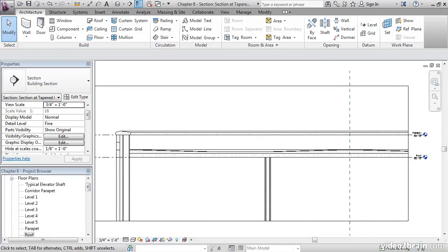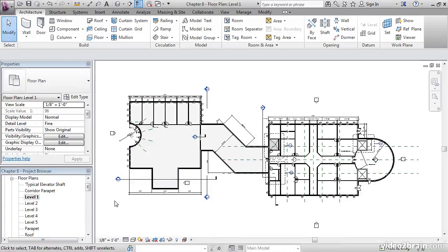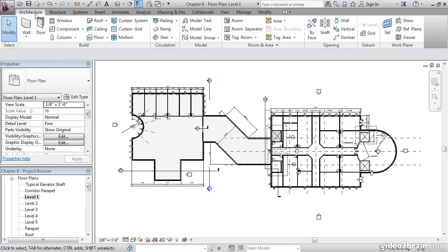So that section's cool, right? We went through the task of splitting our roof, adding all those points, setting them -3 inches just to draw a bunch of lines in plan, right? This section here, and every other section you put in, automatically show the pitch. If you could go down to level 1, type ZA, and hit Save, that concludes this lesson.